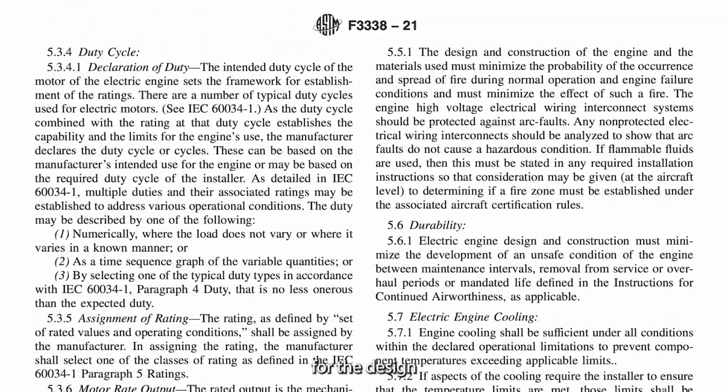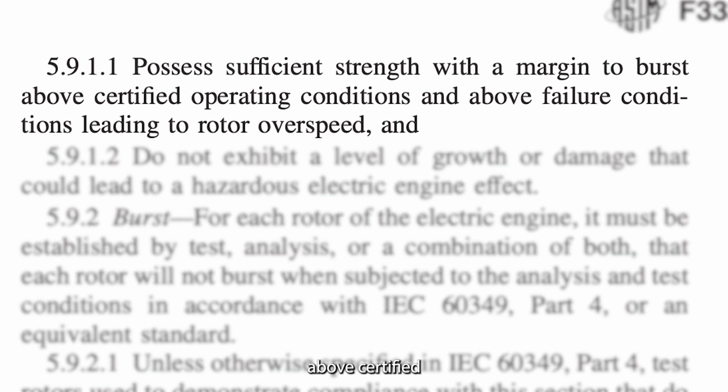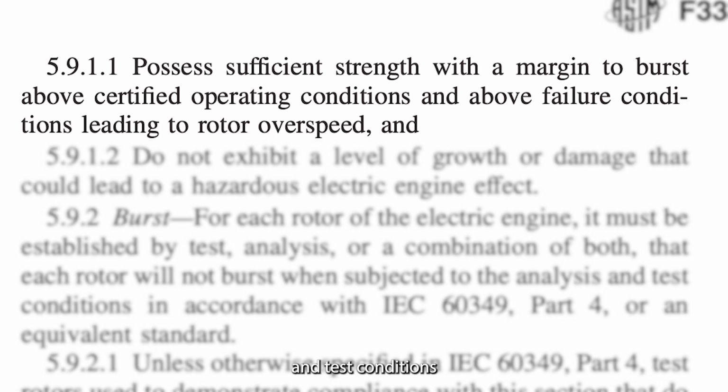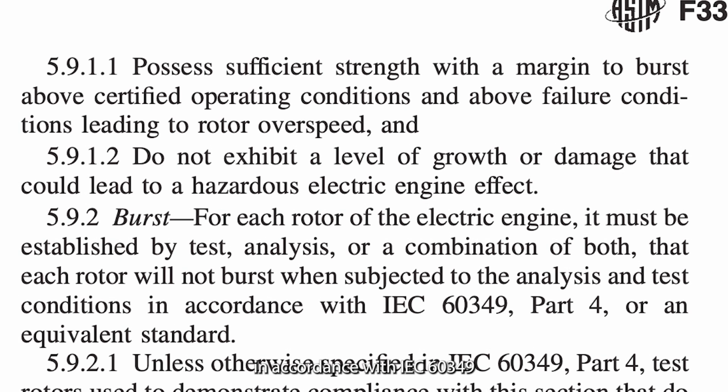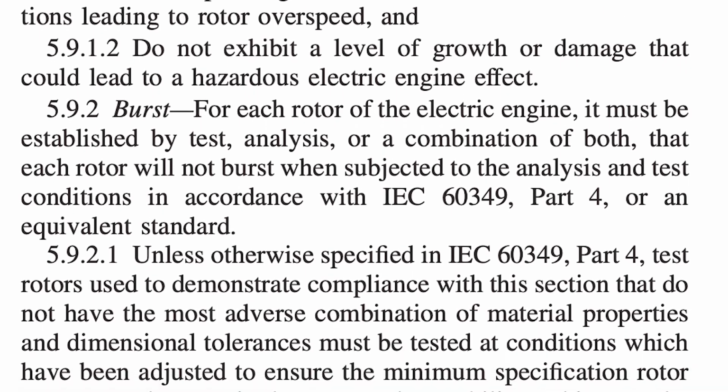Other requirements for the design of the electric engine include overspeed of the electric engine rotor. The rotor must possess sufficient strength not to burst above certified operational conditions and above failure conditions leading to rotor overspeed, meaning the rotor should not burst when subject to the analysis and test conditions in accordance with IEC 60349, Part 4.